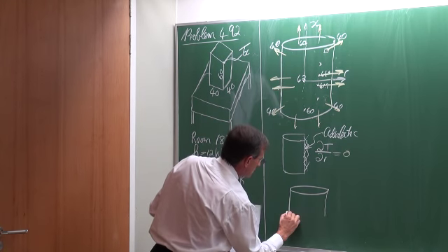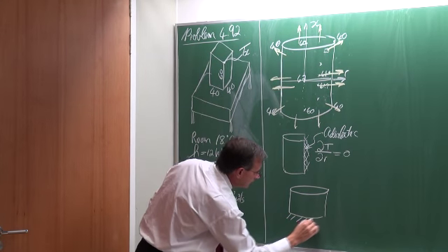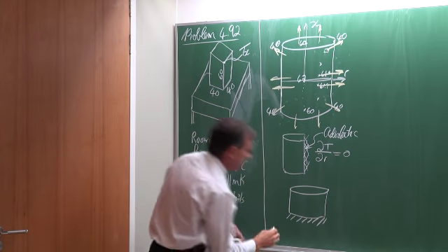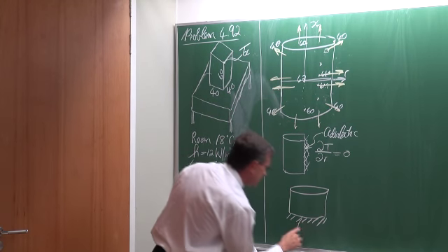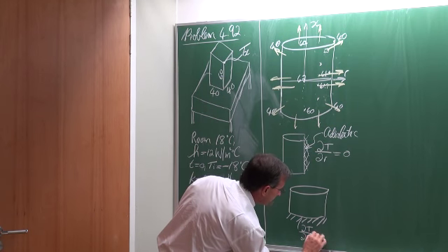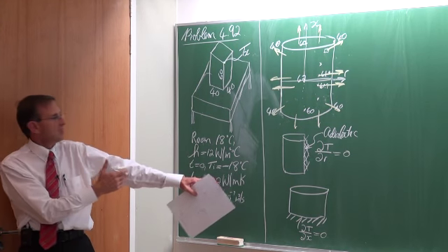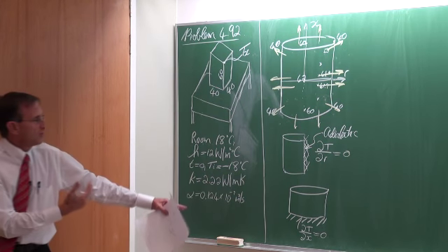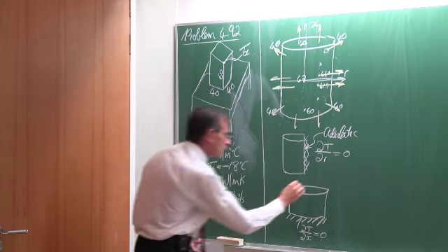So if we now look at only that half of that cylinder, then again it would be as if that is insulated. There's no heat transfer in that direction. Again, it is an adiabatic wall, and now partial dT/dx would be equal to 0. There's a 0 gradient. And you're using these things in CFD in terms of boundary conditions, and we've used similar types of boundary conditions before in the solution of our equations.